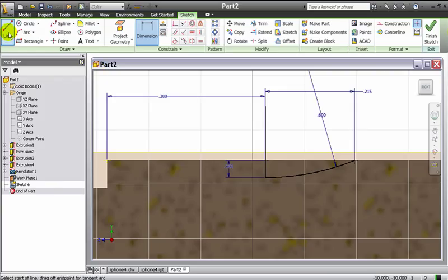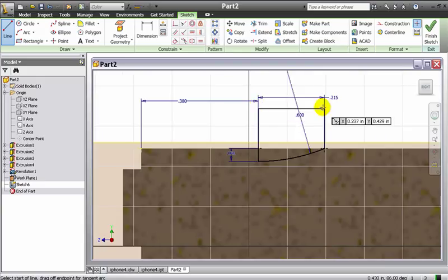Now I'm going to take my line tool and I'm going to lock on to where my line is up here. I'm going to click, bring this over until I'm lined up with the top of this. Click again, and I'm going to finish it off to this point right here. So I got a little arc cutting into the phone, and then I've got this kind of square shape coming off. Make sure that you've locked on green every time. If you have any holes, it's not going to work. This line needs to be completely solid. This is what's going to create our little push button here.